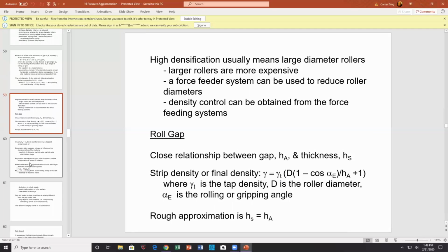Okay. So the longer the roller length, the more production you can get, up to a point where the roller starts to flex on you, a little bit or a lot. So that may indicate that you have to buy 2 or 3 rollers, not just 1 roller. Scale up is by increasing size of the equipment, that's true, or by increasing the number of equipment. Scale up is done by number. Scale up is done by design or simply repeating what you already have.